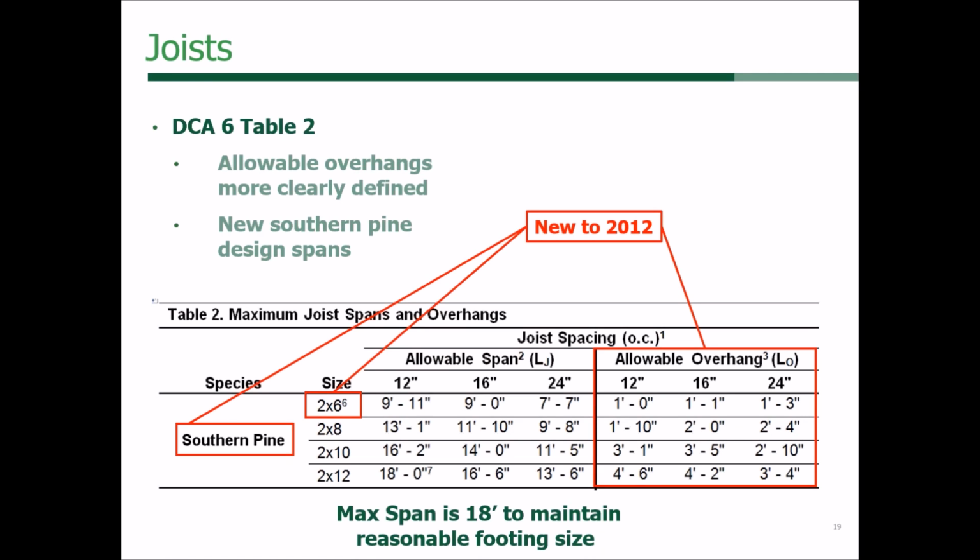And the further out those supports are, in other words, the larger the span is, the less stiff it is to resist deflection. And so when you have a 7-foot, 7-inch main span with 24 inches on center, you're actually allowed a little bit of overhang. But overall, if you use 12 inches on center, you're going to be allowed a much larger deck.